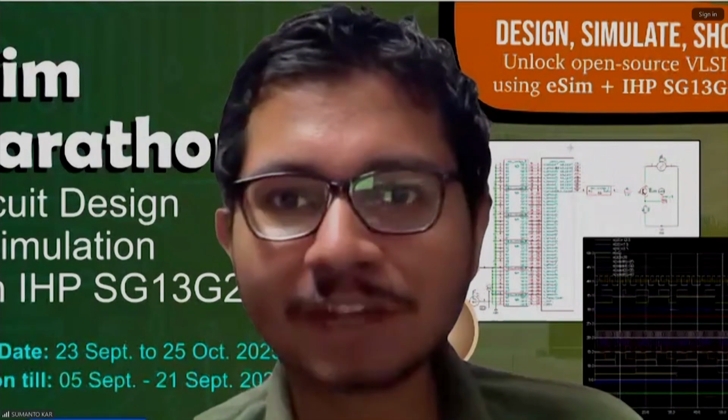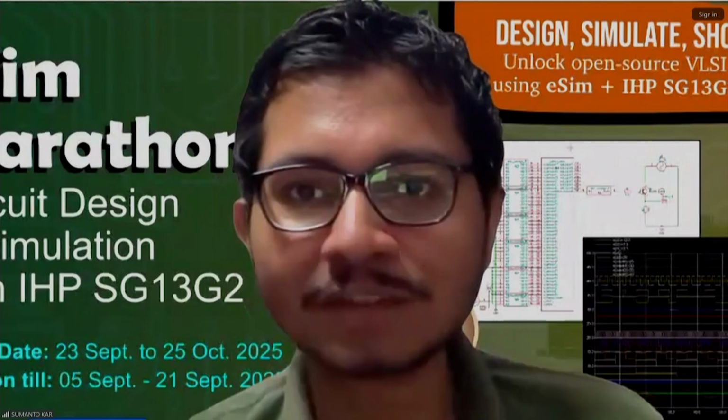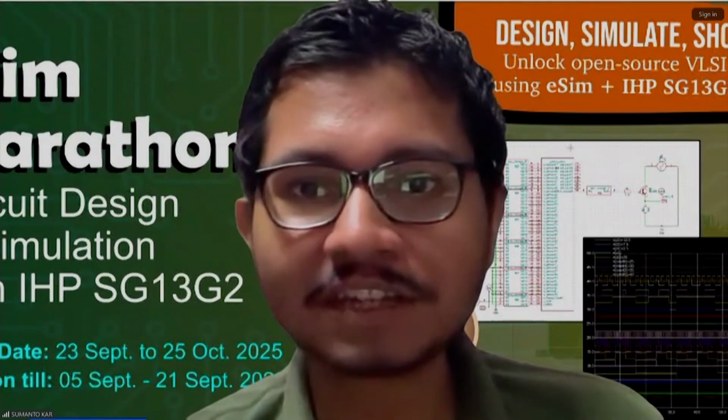Another question. I would like to know your views on the benefits and challenges of integrating Ngspice into open source EDA flows versus proprietary CAD toolchains. This is ongoing. We have these PDKs. We have the Skywater PDK, which has been designed by Tim Edwards with Ngspice in mind, so it's fully compatible with Ngspice. I guess the same is true with the GlobalFoundries PDK, but I didn't use that one up to now.